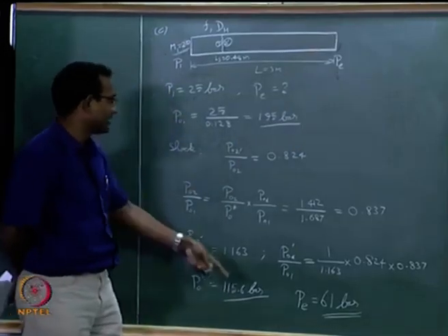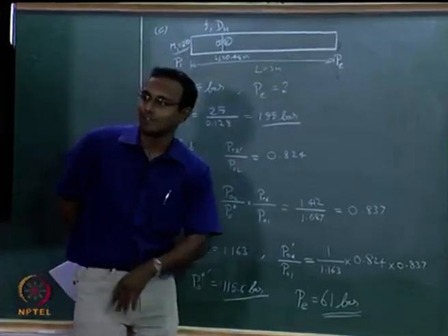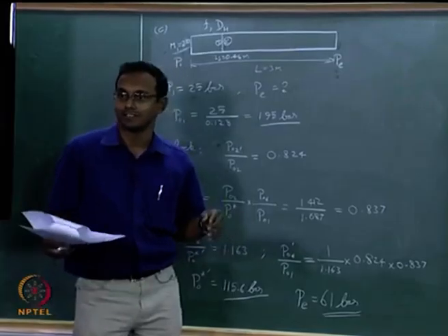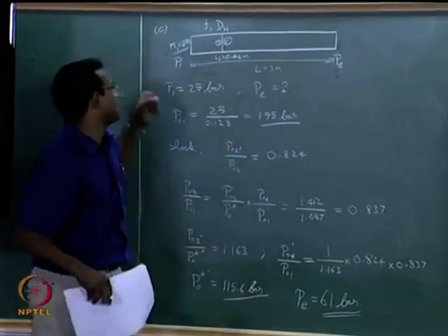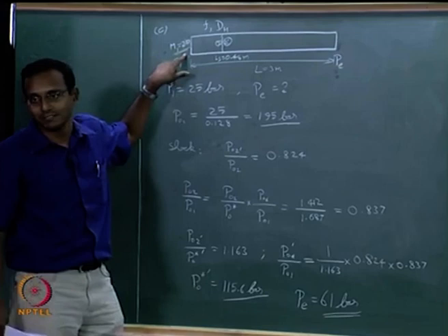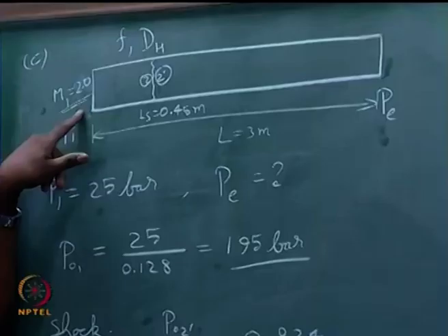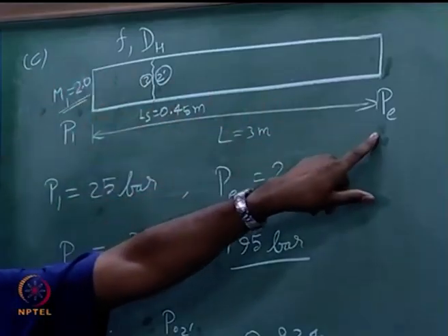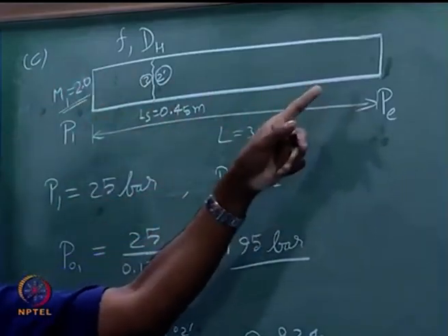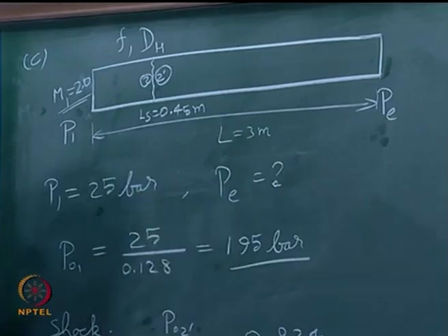That is why it is matching. Otherwise, the flow will never go from low pressure to high pressure. Think about it. But I had other energy, not just pressure energy. I had other energy also in here, momentum or kinetic energy I had, in excess, and that is now decreasing, and that is becoming pressure energy during the process. That is what has happened eventually.